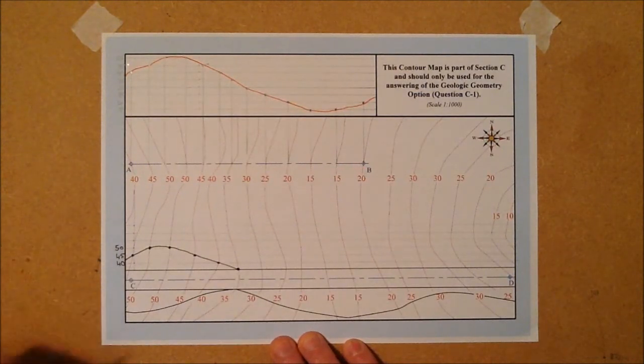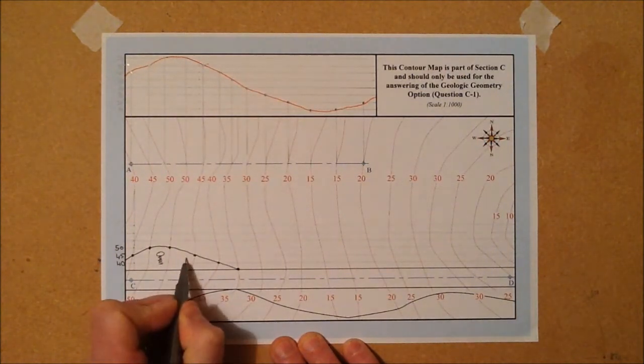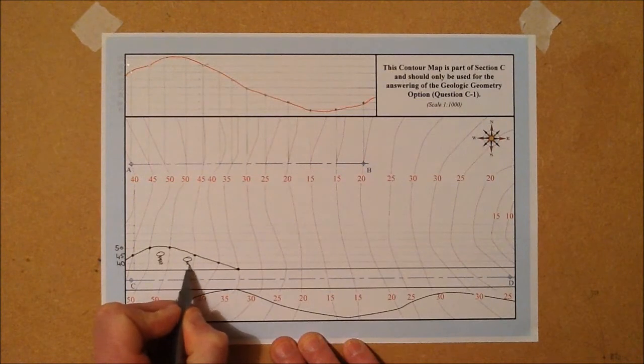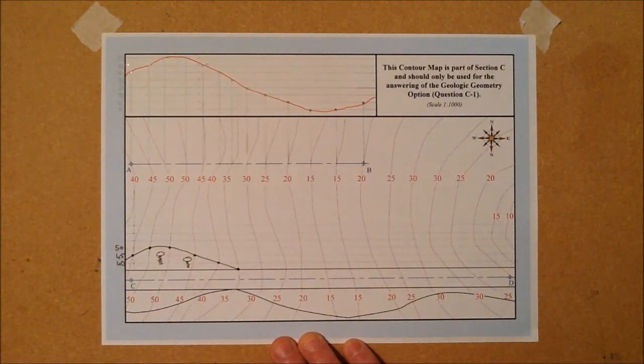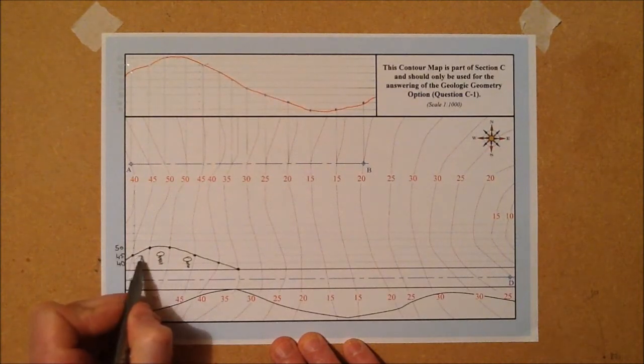One thing we need to do with this is draw in our little tadpoles, just to determine which way the cut or the embankment is rising. Generally the tadpoles swim uphill, so put them in just to give you a bit of direction on which way the hill is going, so we know by looking at them whether it's going uphill or downhill as it goes away from the road. In this case it's going uphill because we cut into the land.